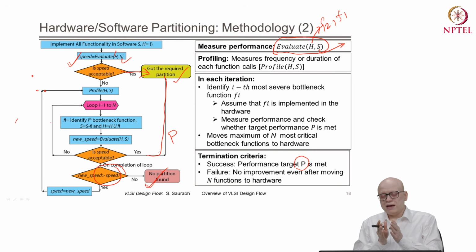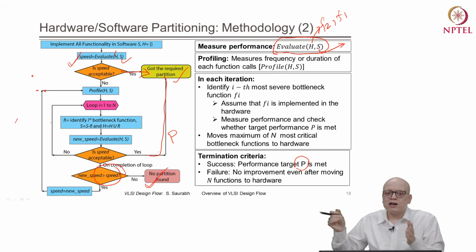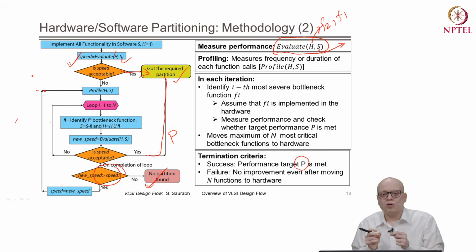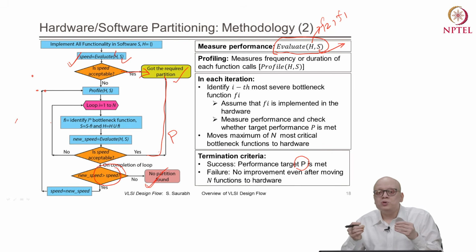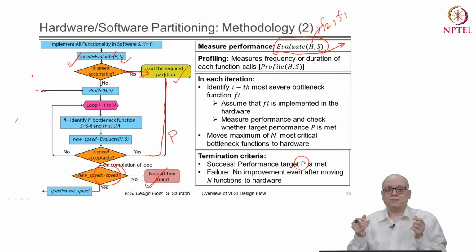See, when we implement everything in software, everything is going from software to software and so on, right? But when there is a partitioning between software and hardware, then there will be a time taken in the communication between software and hardware also, right? And there will also be dependency among the data, and it may be that hardware is waiting for the data and therefore it cannot produce the result even though it is ready, right?